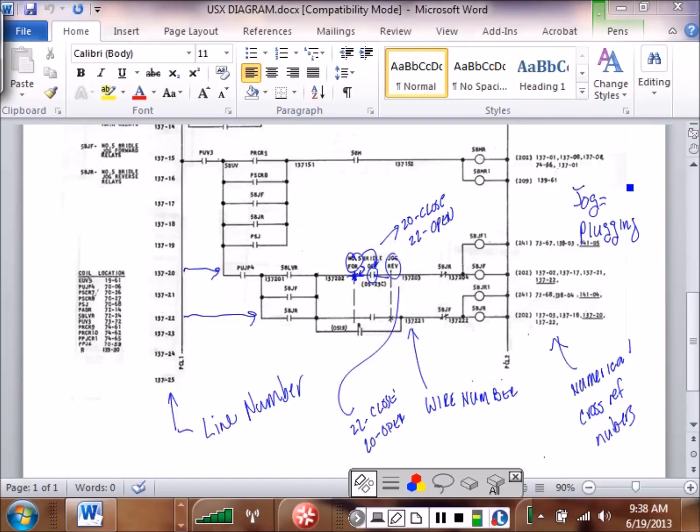So this has, we've got an anti-plugging switch in here somewhere. I'll have to find it, where it deliberately, we'd have to wire that into the circuit. It does not let you change the direction until the motor stops if you wire it correctly. Are we okay?